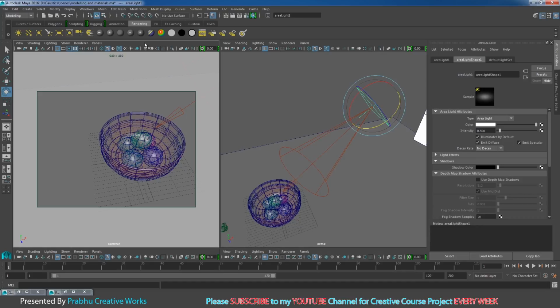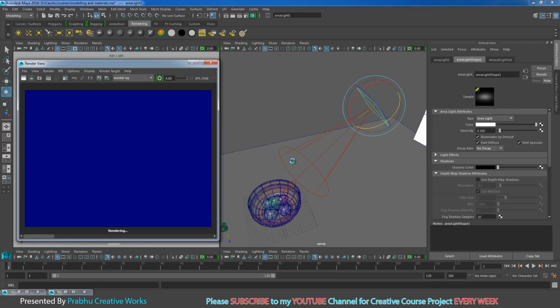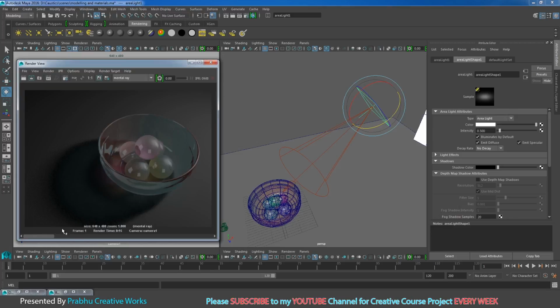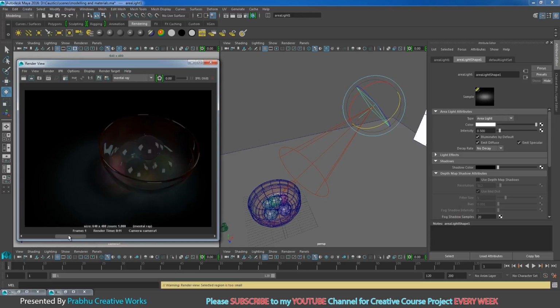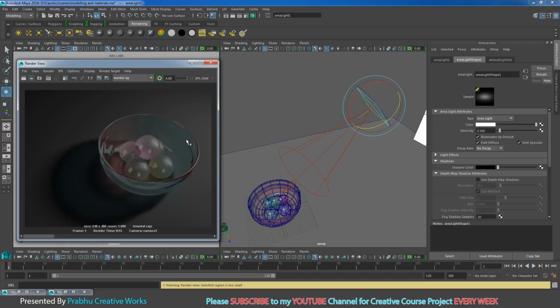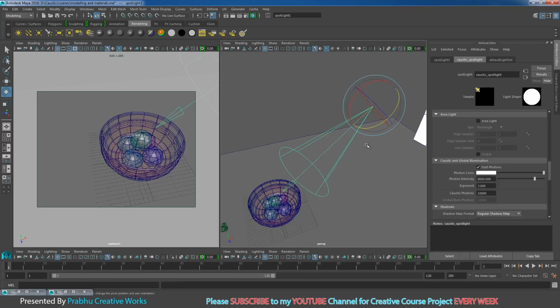So I will select my view and go to render view. I will keep this image for comparison and click render again. Okay, see here we have a realistic crystal cup and ball effect. Now we want to tweak our caustics for our final. So I will select my caustic light, the caustic spotlight.